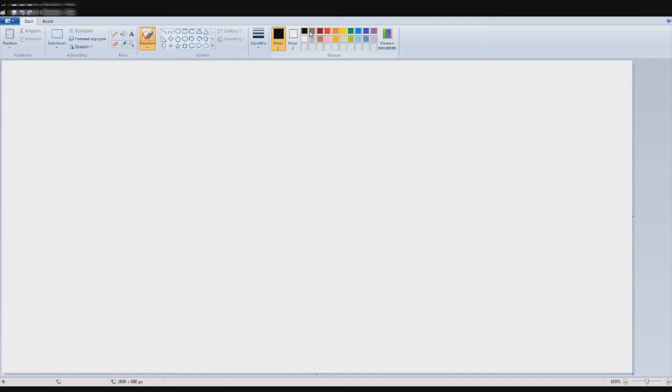what you would usually model the railgun as in a form of component, which is a resistor, obviously. So we have a voltage source, which could be a capacitor or anything, and the first thing we will find in a capacitor, for example, is the resistance of the capacitor itself, which is the ESR, equivalent series resistance.